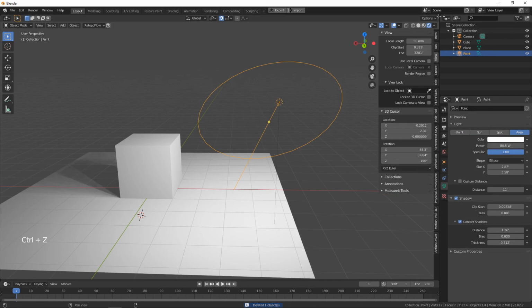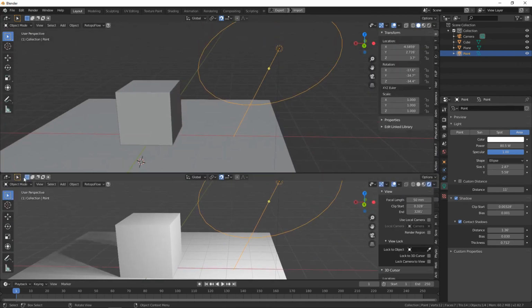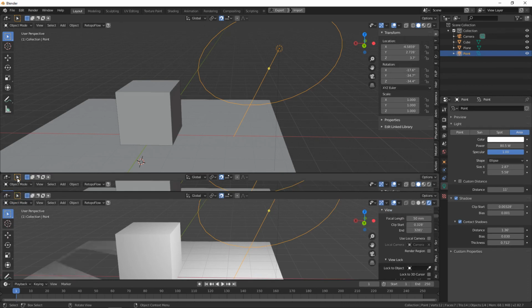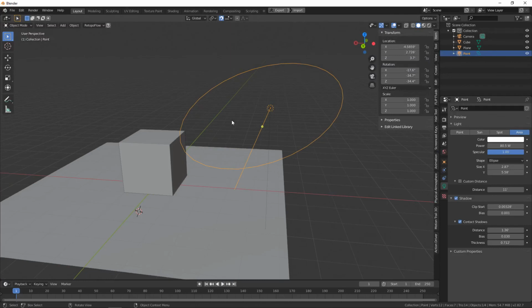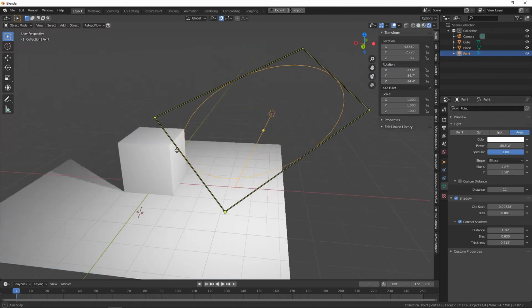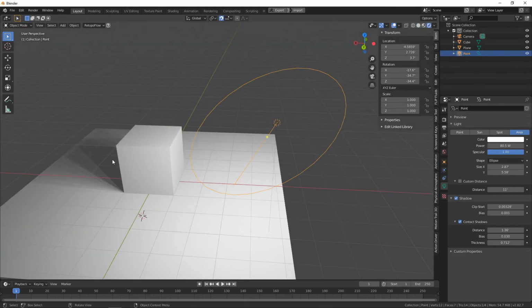With this glitch, it's just a bug. There's been a bug report, but I haven't seen any updates on it in a while. So to get around this, all you do is drag out a new window, remove the old window. Whoops. Sometimes in Blender you get to this state where you're constantly pulling out more windows. So if you right-click on this window, click Join Areas, you can join areas down. And now if I go into rendered mode, it's fixed now.